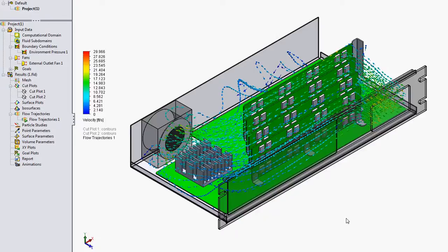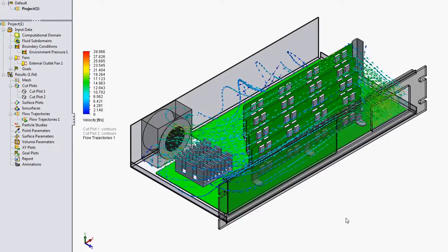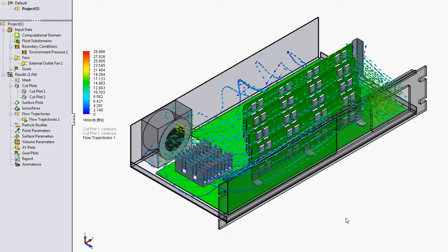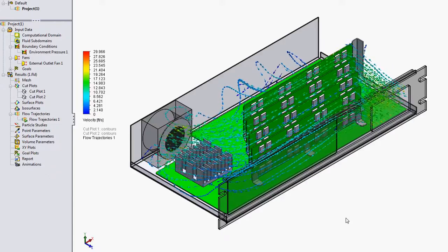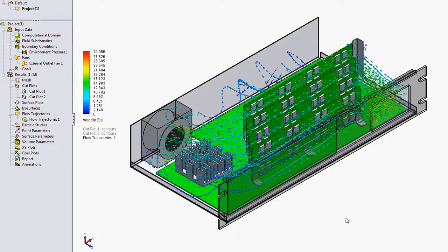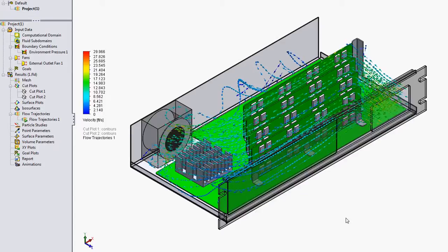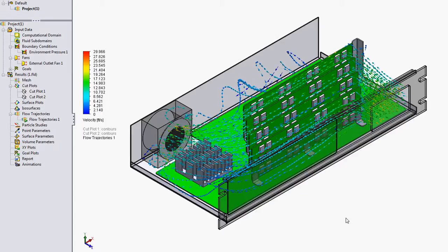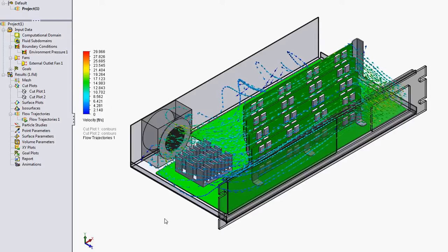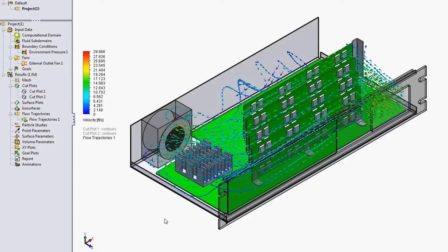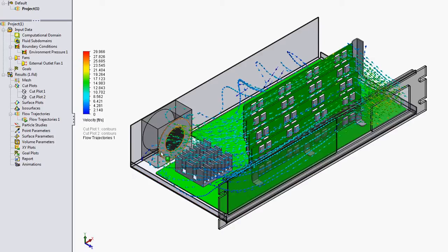So basically if I go through and create a pressure resistance curve for a box, I'll just multiply that by 2 times, and that band that's created between 1 and 2 is what I'll be using notionally to size for a fan. So based on the resistance curve and the amount of power you are trying to dissipate for a given temperature rise, you can select your fan. For this model right now, I'm just using a 70 CFM open airflow Mil 80 fan by Amatec Rotron.